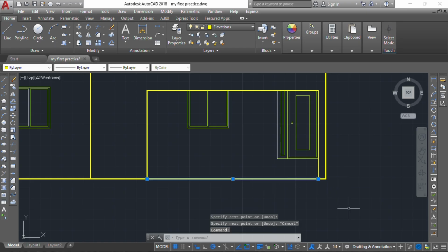Basically, for us to be able to design our steps or staircase, we need to consider some things, right? The riser must not be too high, with a minimum height of, let's say, 150 or 200 is okay. And then our tread should be a minimum of between 250 to 300, right?